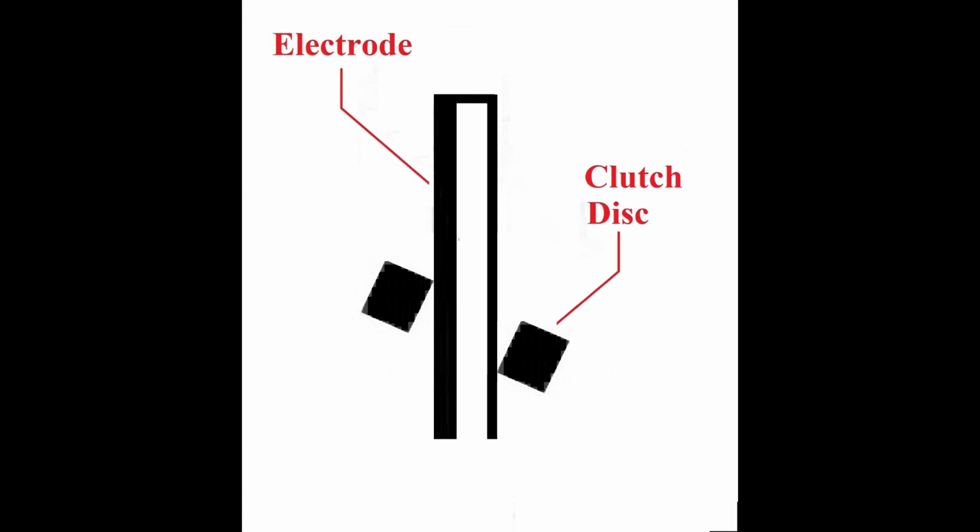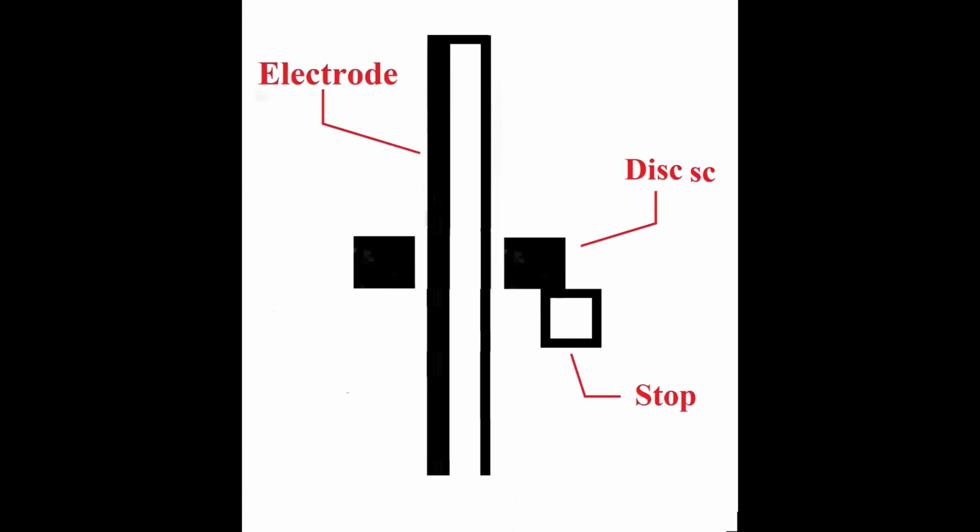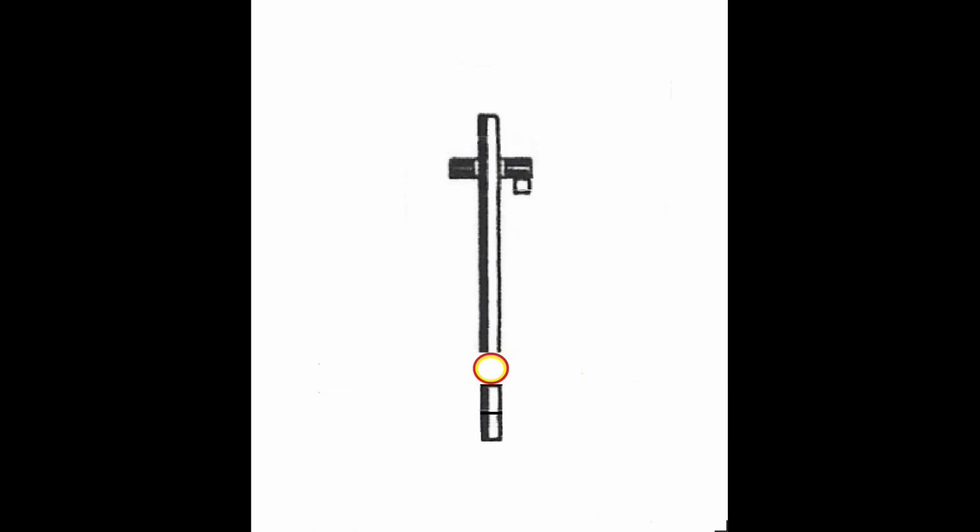Notice that in our description up to this point, the clutch has been tilted, grabbing the electrode. This allowed the clutch carrier to adjust the arc under the control of S1 and S2. A stop is provided near the point where the upper carbon has shortened to such an extent that it needs to be fed downward. When the stop is contacted, the electrode drops down, shortening the arc. S1 and S2 react to the change in voltage across the arc, pulling up the clutch carrier and causing the clutch to tip and grab the electrode, at which point the control of the arc is reestablished.